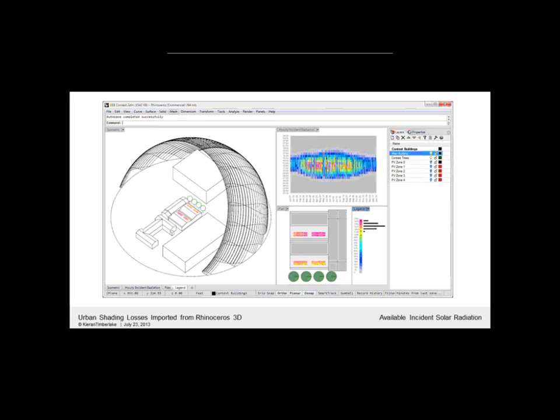So by sampling fewer analysis points, typically 1 point per PV cell, we could very quickly calculate incident radiation for all 8,760 hours of the year and map those distributions graphically onto the PV panels. This would allow us to refine the placement of PV panels to minimize overshading, and it would also allow us to identify areas with similar shading conditions so that we could string panels together to minimize losses due to mismatch.